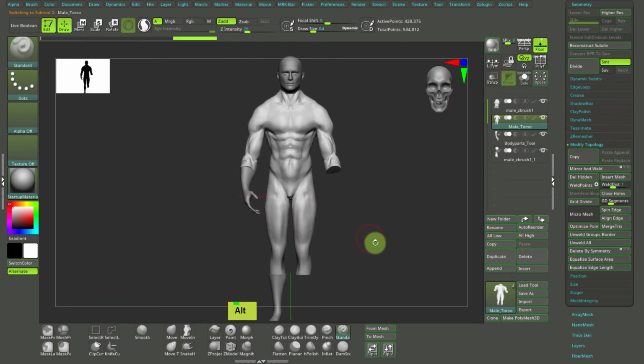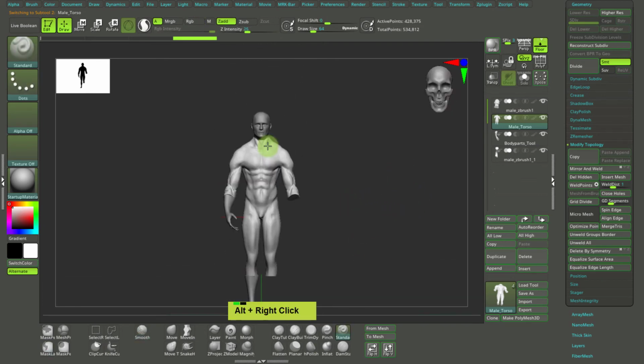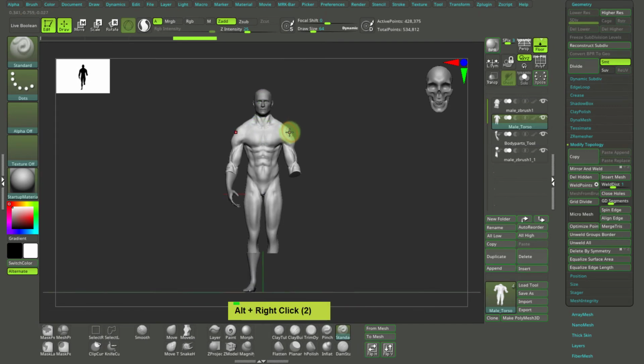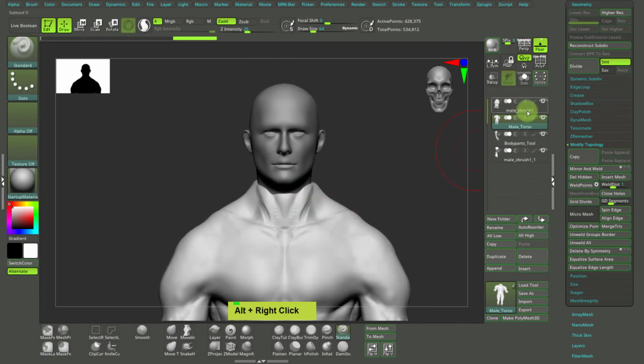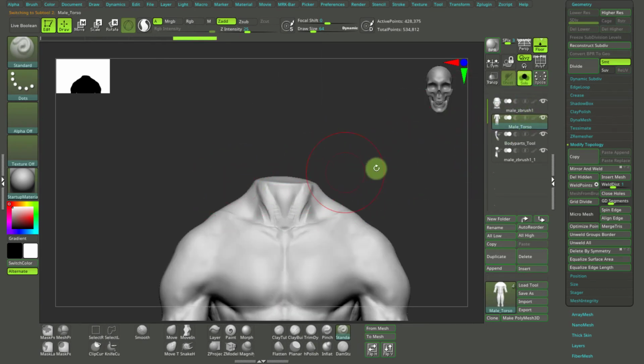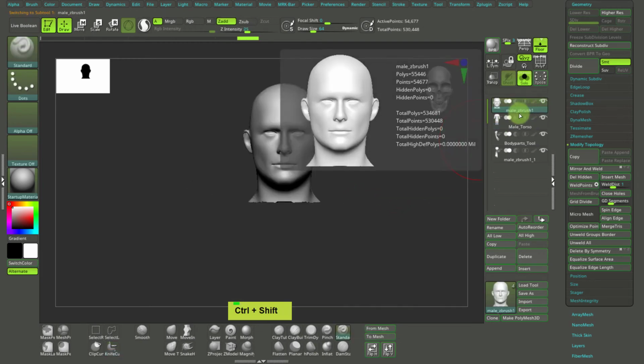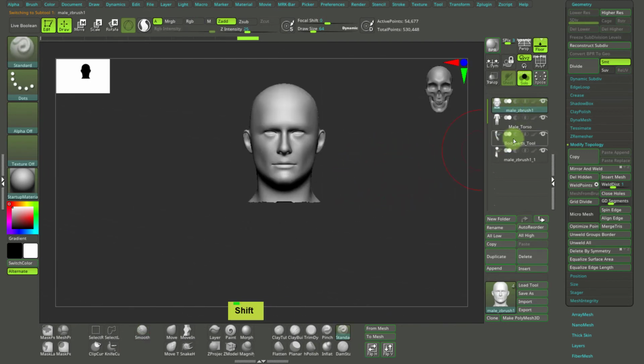Now, before we are welding, of course, this is kind of a preparation at the very first stage, and we need to fix the joints, and then we will make the welding. Okay, so here comes now fixing the joints, the meeting area. So I will select the body, and only the body in solo mode. So I will cut this flush. So Ctrl Shift and drag. You can see the shadow is pointing upwards, so that means the top part will be removed. And setting back, and here's the head.